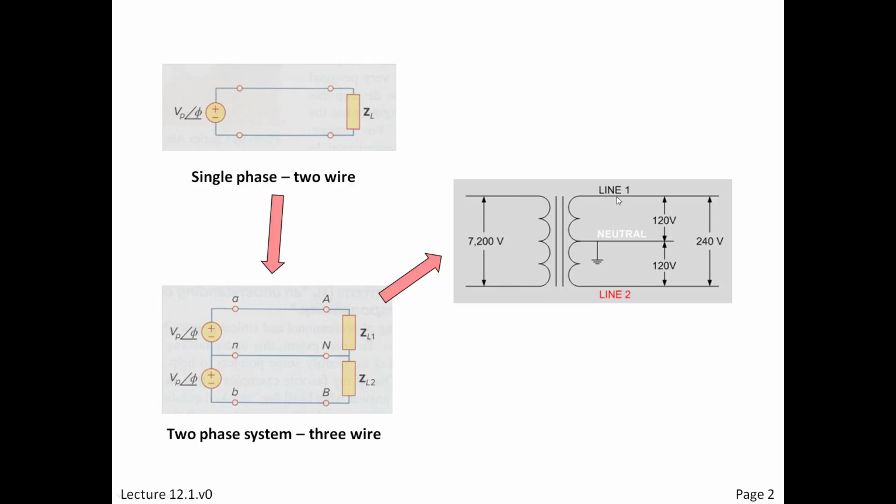So this then breaks the power down to be 240 volts. This is about a 30-to-1 ratio in this picture, always an integer number. And more than that, the 240 volts is broken in two by something we call a center tap. So it breaks it in two, into the two very common 120 volt lines or voltages that we're familiar with, distributed in our house, in the residential house.